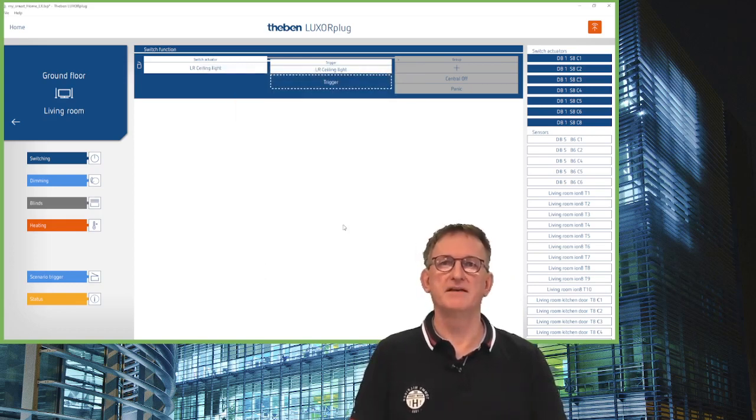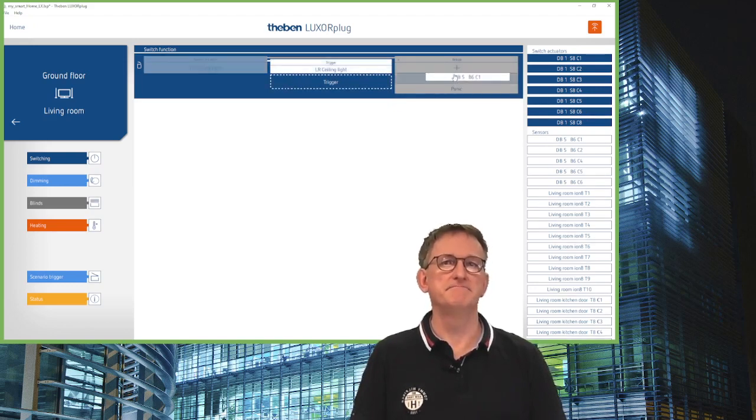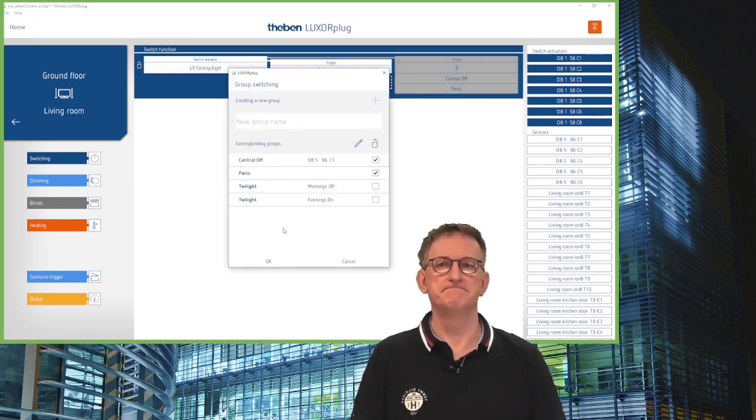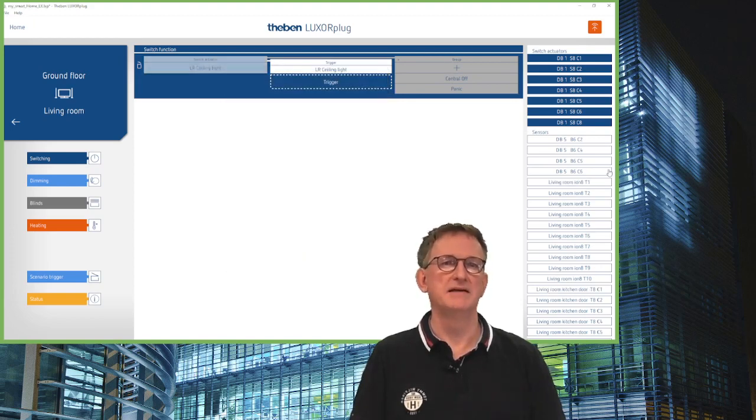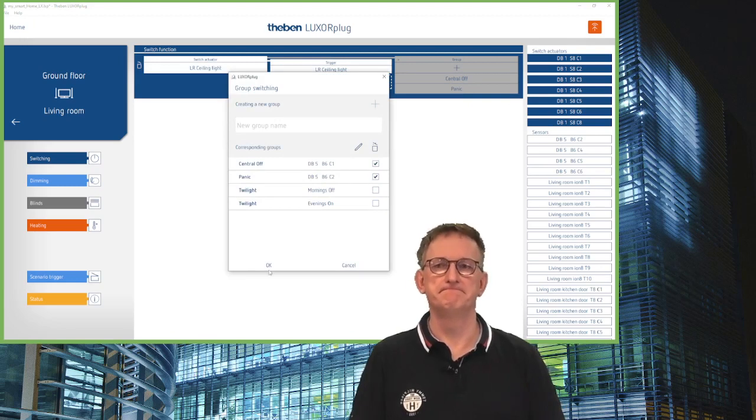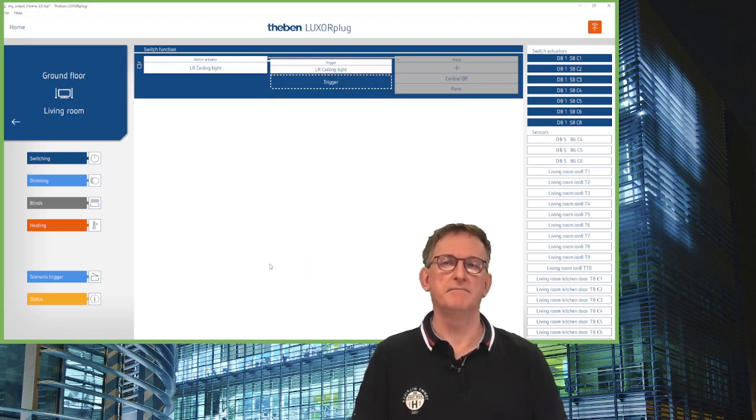Okay, say okay. And in that case, I also will assign the central functions, central off and panic right now. And that's C1 is central off. I will just say okay. And C2 is panic. Okay, so the first switching channel is programmed.